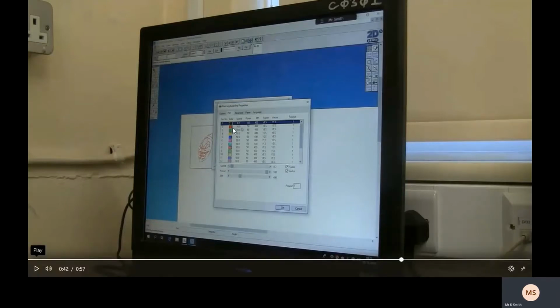Now for the engraving, I just want it to burn the surface of the material. For this situation, you can change it to whatever you want. So you could have it on full power but really quick, so that it's powerful but not so slow that it will burn all the way through. If you put it on a really high speed, it'll quickly go over it at a powerful setting, but it won't have time to burn all the way through the material.